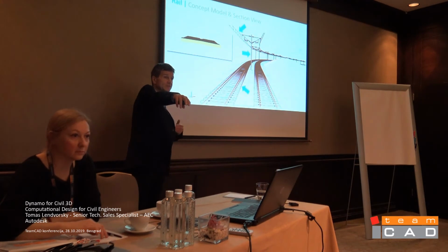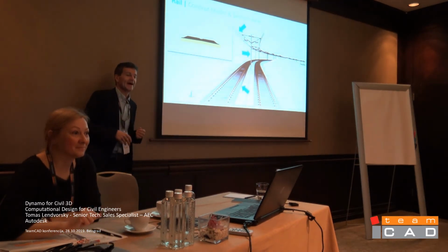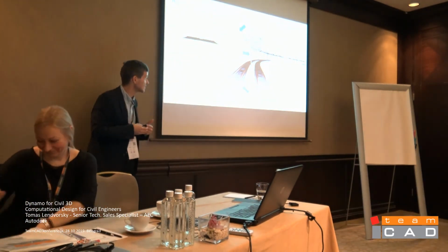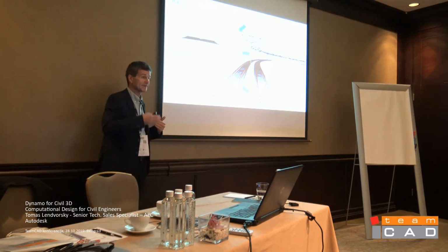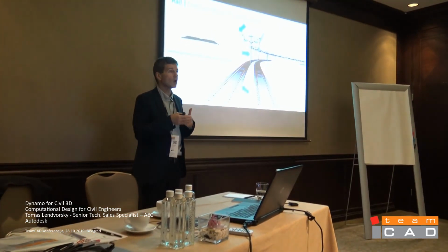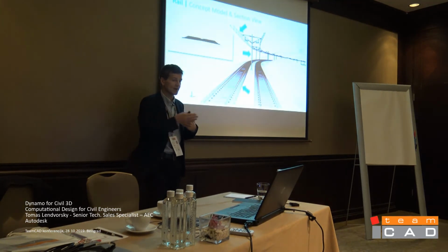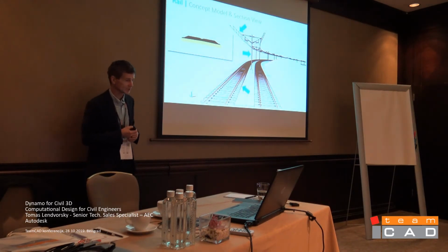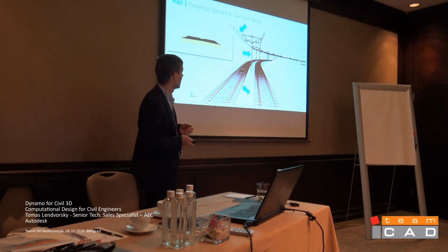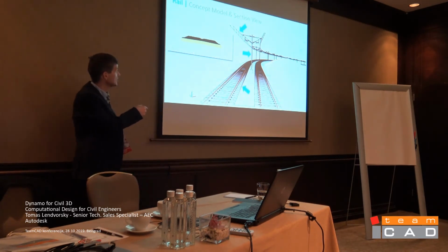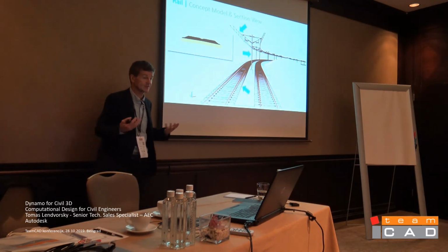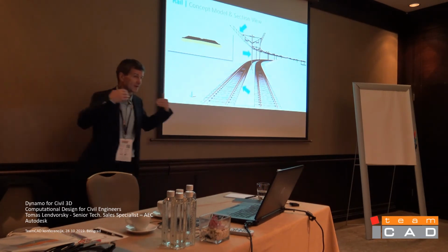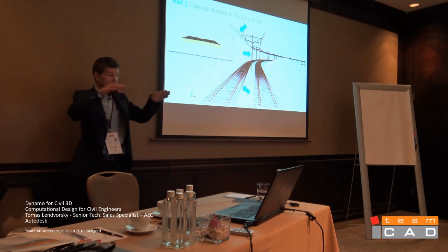So basically what you can do is place these objects at some regular interval, but again you should do it along the geometry, because the system should know where the alignment is, where the profile is, where the surface is, and put it along this. In Civil 3D you can predefine a typical cross-section, basically an assembly, and run it along the alignment and profile to create a corridor.